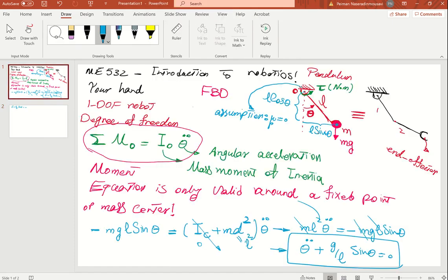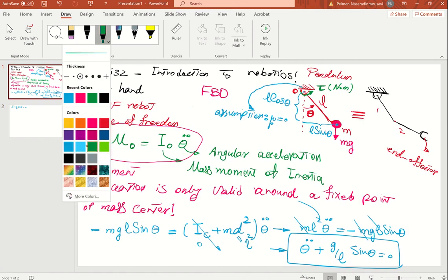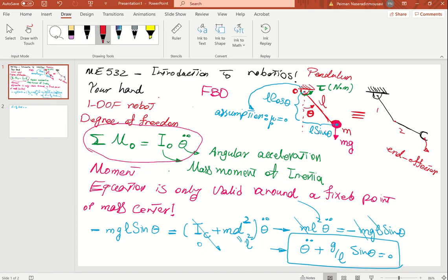But I want to control the system. That's why I apply the external torque here, guys. Because I'm going to go to Matlab, here the only force is not the mgL. Because tau is helping the motion, see the direction of the arrow, so it is tau minus mgL.